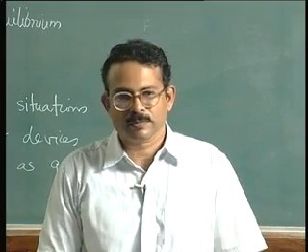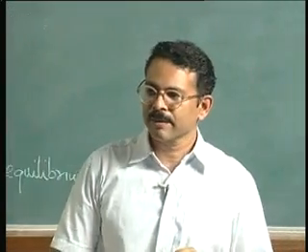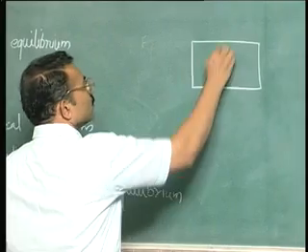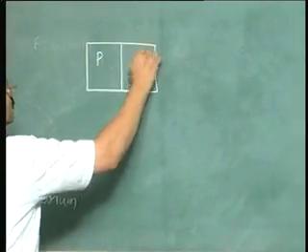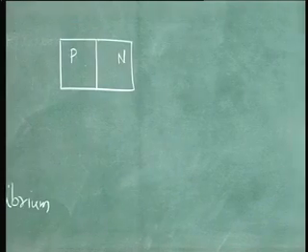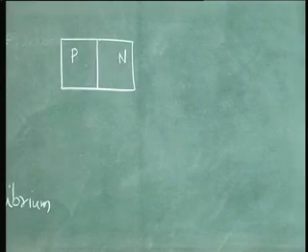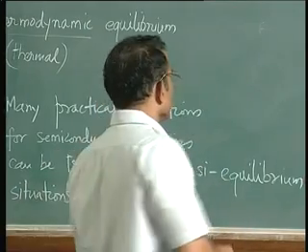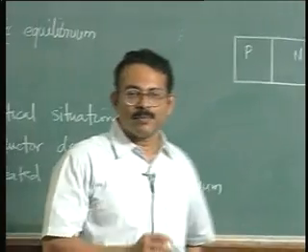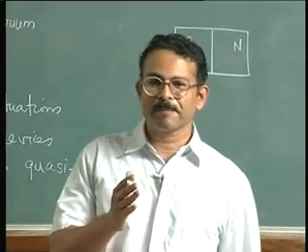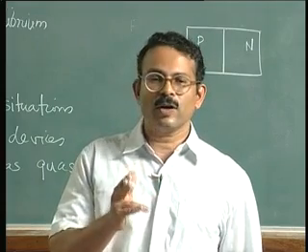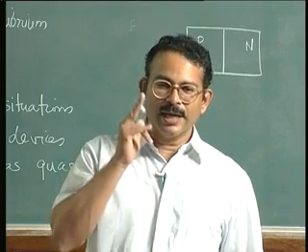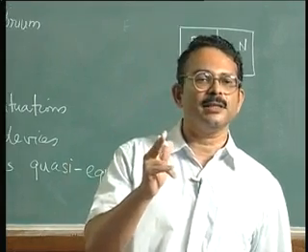We will take an example. Let us take a PN junction. What I am trying to tell you, you must accept as facts because we have not done an analysis of a PN junction. So you just accept it as a piece of information. Across the junction in a PN junction you have a very large current density even under equilibrium conditions for electrons as well as holes. But what is important is that current density in one direction is exactly balanced by current density in the other direction.